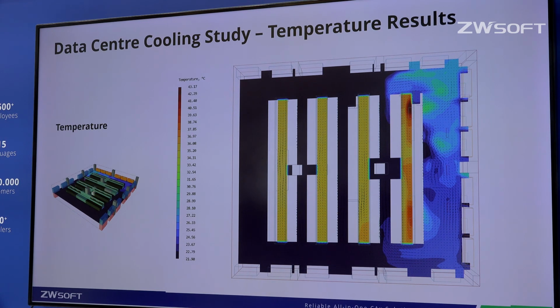In the top right, we can see that there's a dark red region as well, which is inside one of the hot aisle containment parts. This indicates that there is a server that is running hotter than it would be expected, and this is likely due to the warm air that is in front of the server. So this means that that entire row really is not being able to cool down as effectively as the designers might desire. So let's see if we can find out what's happening here and why this is taking place.